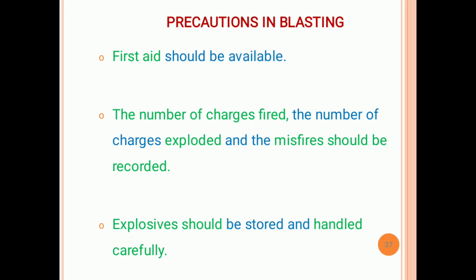The number of charges fired, the number of charges exploded, and the misfires should be recorded. So when you are drilling holes and placing charges, you should count the number of holes, and you should know how many explosives, how much charge you have placed, because any mistimed charge that has not exploded may still be in the hole.